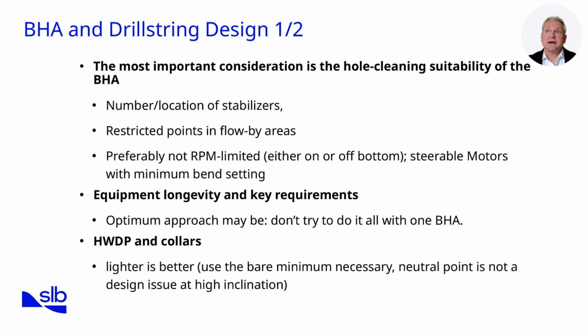The first part of the BHA and drill string design emphasizes hole cleaning suitability. In ERD wells, cuttings transport is often the limiting factor, and the BHA must be configured to support efficient cleaning. The number and placement of stabilizers is crucial. Too many, or poorly spaced stabilizers, can restrict flow-by areas and reduce cuttings transport. We must also avoid RPM-limited designs.